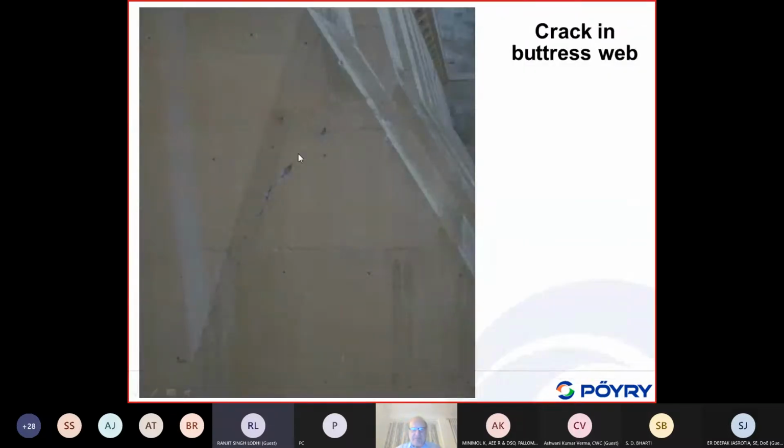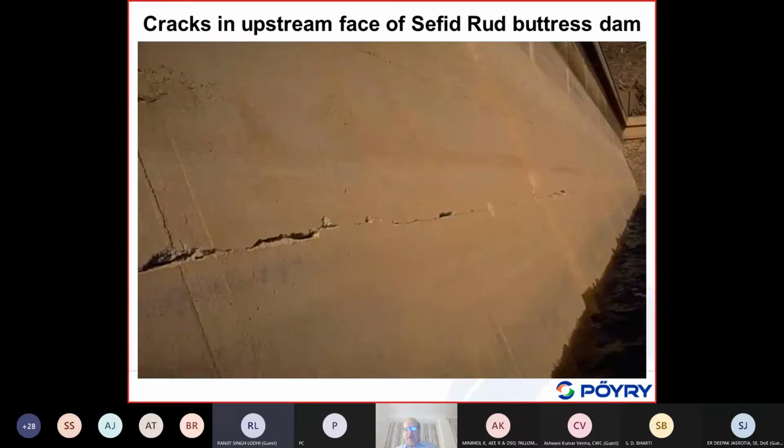We see here from a neighboring block, this one here, the crack does not go sharply along this joint between the head and the web, but you see the crack more or less follows this portion. But it originates here again near this kink, which is this location of stress concentration. So that was a view of the downstream phase.